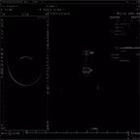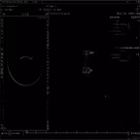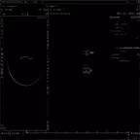And you can actually see this code if you right-click on the VOP and say vex, VOP options, view vex code. Then you get this very verbose list of stuff. And that is the program that your VOP operator is writing in the background. So this is what gets compiled, and this is what is executed. That means, in reality, VEX and VOPs is exactly the same. VOPs is just an interface for VEX. Instead of writing, you can use nodes to code, and that is a great thing.